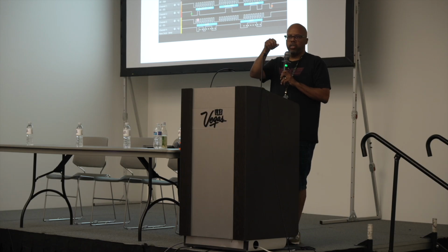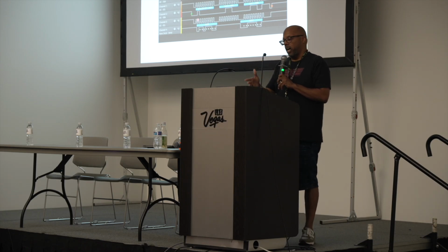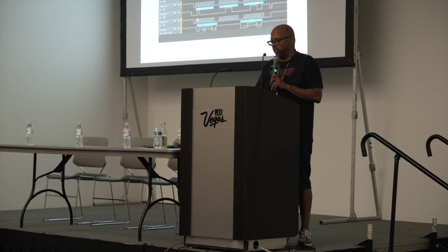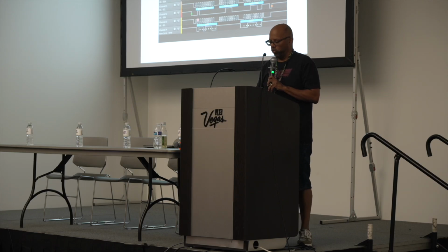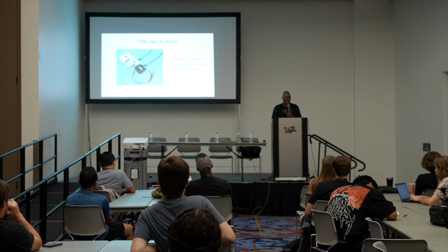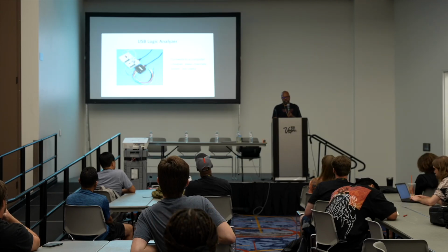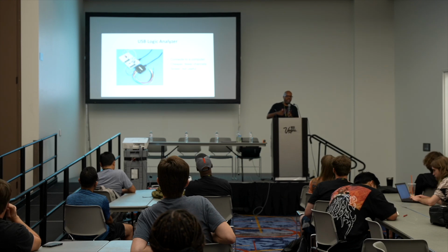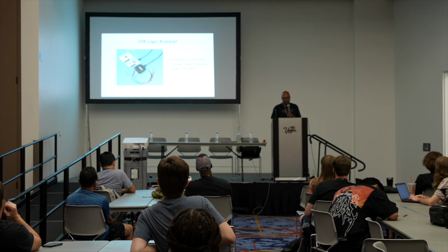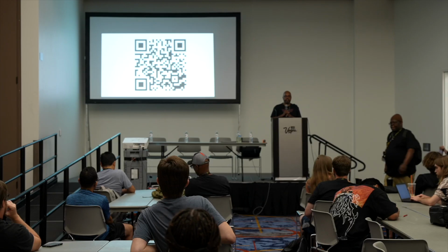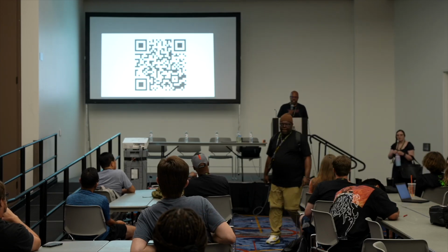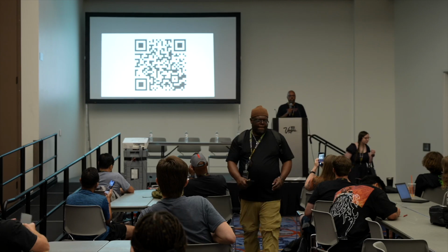Anyway, these are useful like that. And they're usually very smart too. They know protocols, like I2C, so they'll just mark it up for you. It's pretty useful actually. Here's one that I have, a USB logic analyzer, connected by USB to my laptop. You download a free app and you can record and do stuff with it. And it's got a lot more wires that you can use to probe. And that's about it. You can download the slides if you want, and let me know if there are any questions.